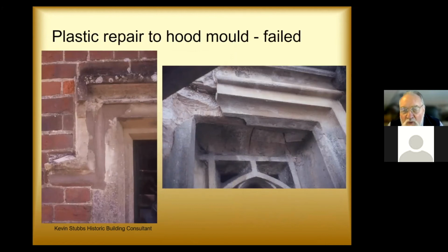So we need to repair those hood mouldings and copings, etc. What is not a good idea is to use lime and stone dust type repairs where you're going to get maximum weathering. And so here, the proper way to have done this repair would have been to actually cut and piece in new pieces of stone to shed the water effectively.